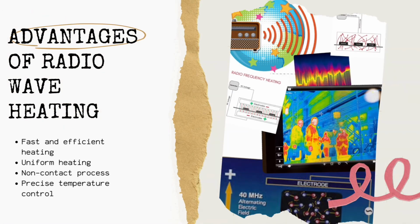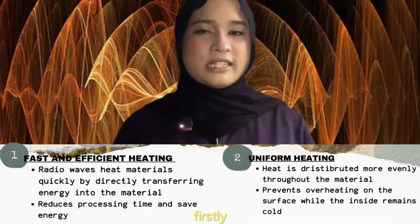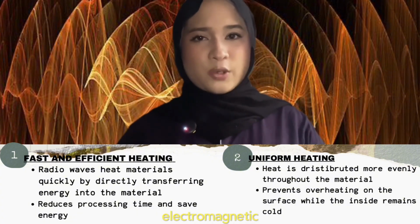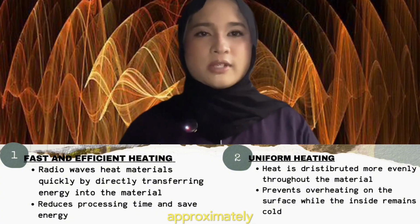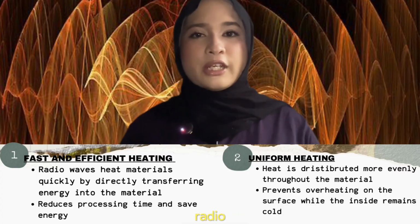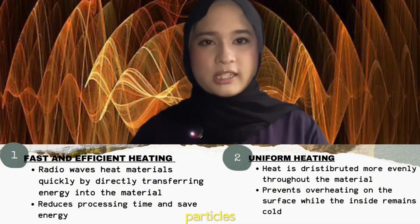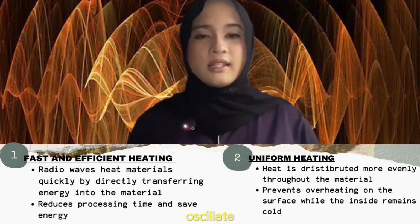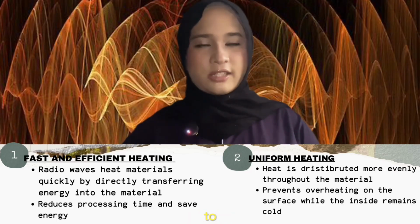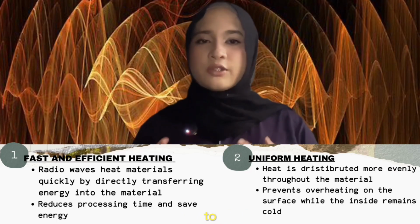Now, I will explain the advantages of radio wave heating. Firstly, radio wave heating provides fast and efficient heating. Radio waves are a type of electromagnetic wave with frequencies ranging from approximately 3 kHz to 300 GHz. In heating applications, radio frequency waves interact with certain materials by causing polar molecules and charged particles inside the material to oscillate. This molecular movement creates heat energy directly inside the material, allowing the heating process to occur faster than conventional methods which transfer heat from the outside surface to the inside.